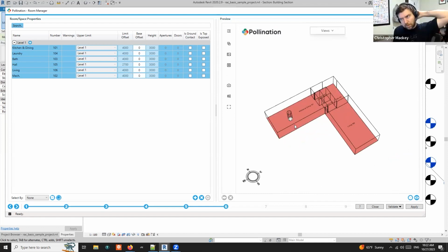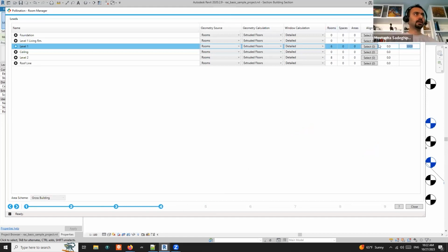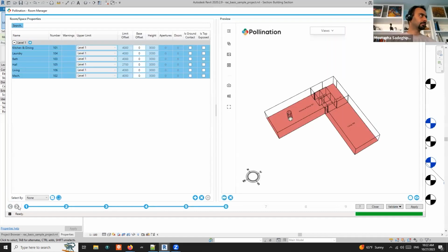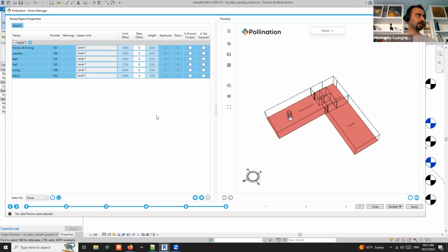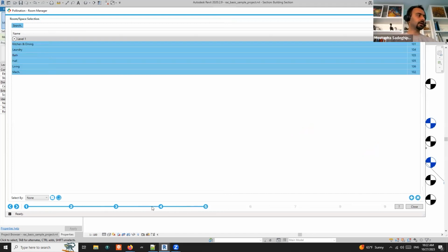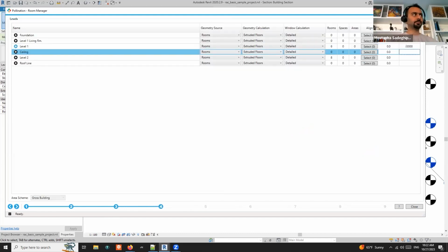Chris? Yeah, Mustafa, there's just a question about, I think a number of people had their extrusion height set to what was the default, which was 3,048. Yeah, if you go back to the menu, because you didn't set it here, then I think Revit tries to figure it out, or the plugin tries to figure it out. Mine is apparently because I set it once. But if you write the exact value, I think it should take the exact value from here.